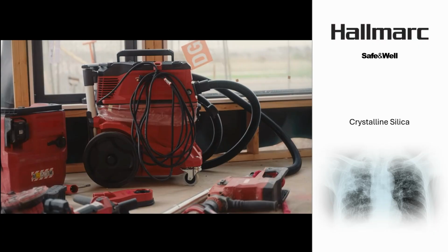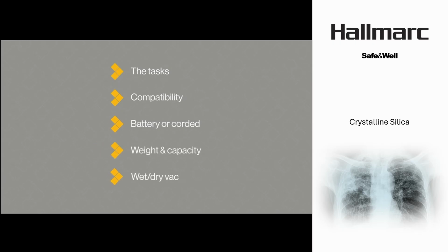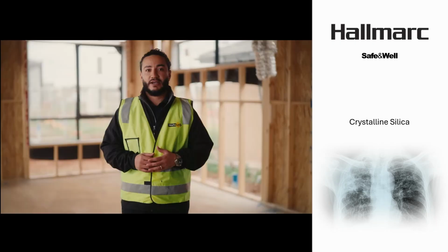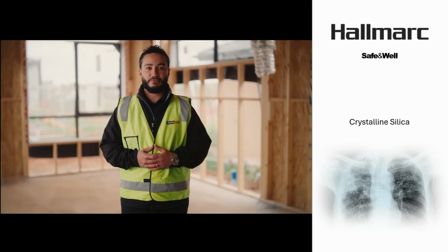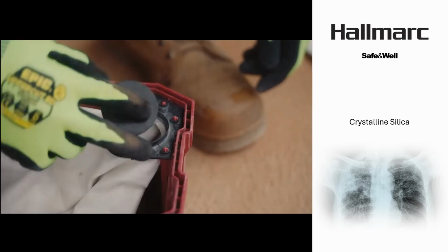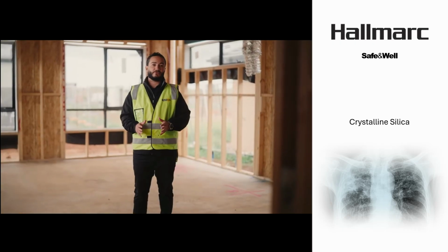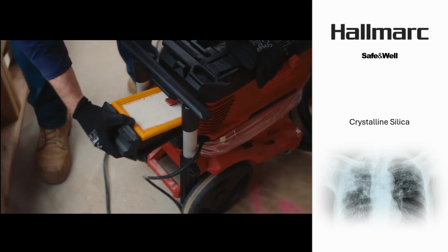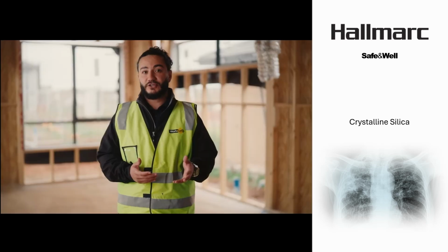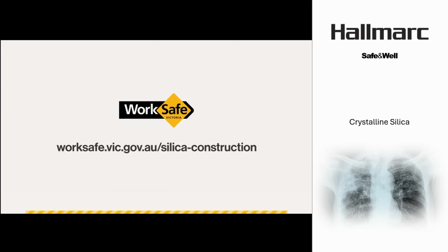It's important to choose the right vacuum for the job. Some things to consider are the tasks it will be used for, its compatibility with power tools and attachments, whether it's battery powered or corded, the weight and capacity, and if it needs to be a wet and dry vac. As you plan for your job, if you have any questions about the equipment, speak to the manufacturer. Waste management can be a source of re-exposure, so disposable bags inside the vacuum can be used to capture dust for easier and safer removal. You should always replace or clean the filters as the manufacturer recommends, avoid using compressed air, and dispose of offcuts appropriately. For more information, please visit the WorkSafe website.